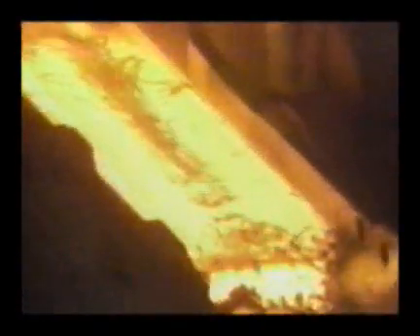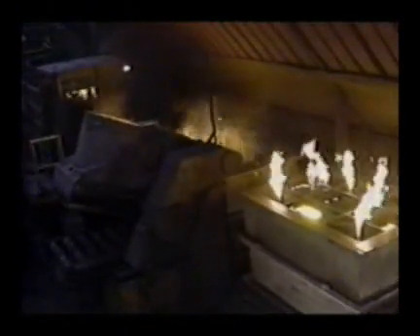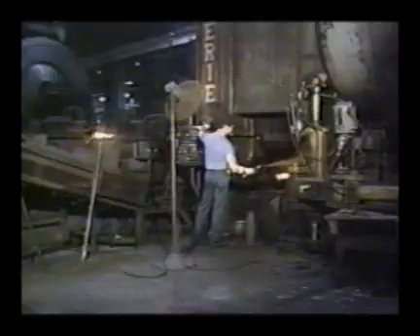Manufacturing processes such as casting, rolling, forging, and heat treating can introduce cracks within the metal. Castings may contain voids due to shrinkage of the metal as it cools and becomes solid. Rolling or forging may fold material in on itself, creating a rolling seam or a forging lap.